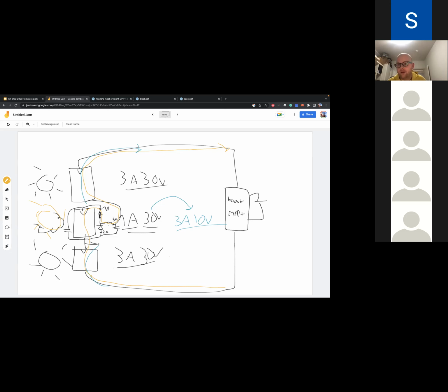What I think you should do, Alan, is IV trace curve individual cells instead of entire strings.